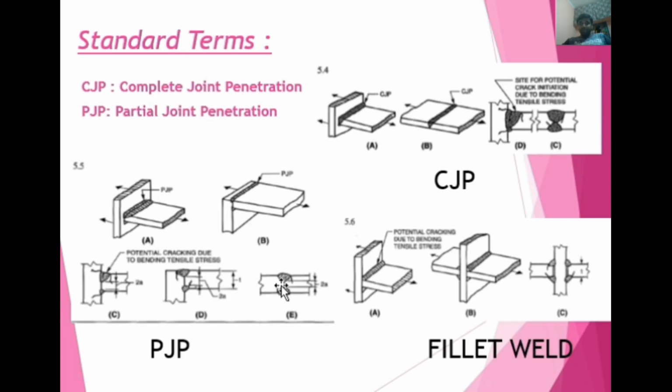In groove welding you can see here, this is the V groove. So this is penetrated and the bottom side is also penetrated. In the middle you can see here the metal is there, it is not melted, meaning it's not penetrated. This is as per the joint configuration. If you go to AWS D1.1, this is the joint configuration. This type of joint configuration will come if you work at sites as per AWS D1.1.